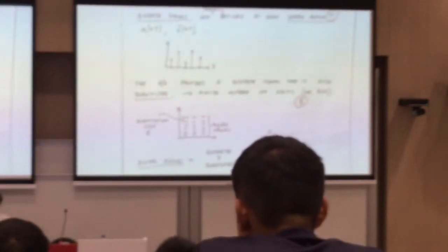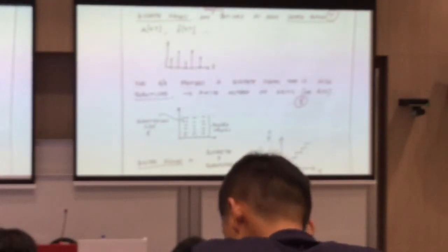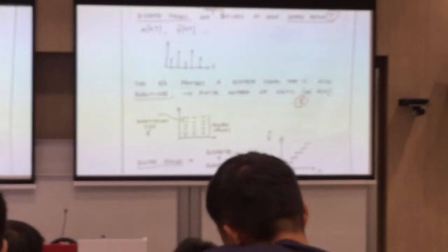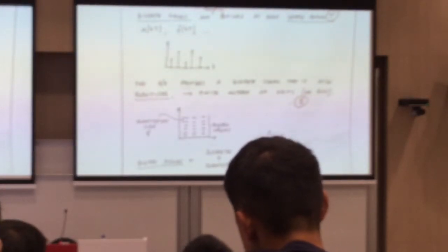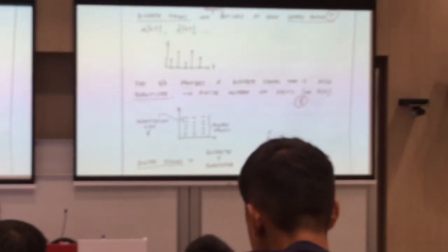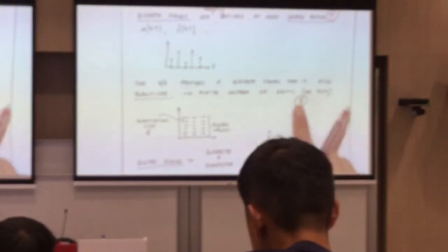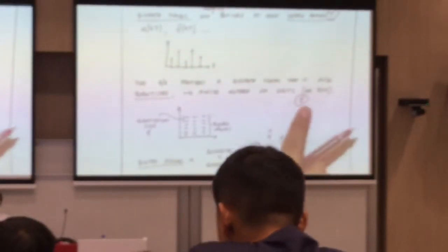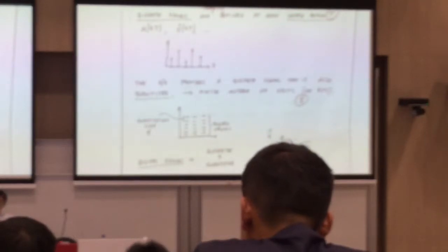Another one is the quantization. Quantization means we are going to use a certain amount of digital memory to represent your data. So instead of infinite resolution, we have a finite resolution. If the resolution is Q, then you may have a quantization error of up to Q/2. So Q is the quantization resolution, and the smaller Q is, the smaller the difference you will see from the analog signal.